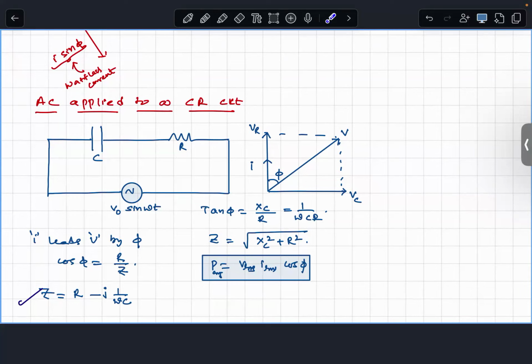But see, total power loss in an AC circuit, in DC circuit is simply V into I. Why is it not V into I in AC? Because that V into I has two components. V into I cos phi, which is accountable under dissipation. VI sin phi is not accountable, and it is not a waste part. It's stored or restored. Sometimes it's in the form of energy stored in the system in a different form, or sometimes that is given back to the system source again.